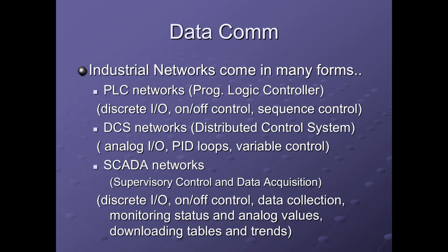They make decisions based on generation, switching, load shedding, and all that when it comes to the electrical power grid. So primarily the big difference is the DCS being a local area network, extremely process focused, and the SCADA network being a wide area network and communications focused. It's all about retrieving that data from a large area.